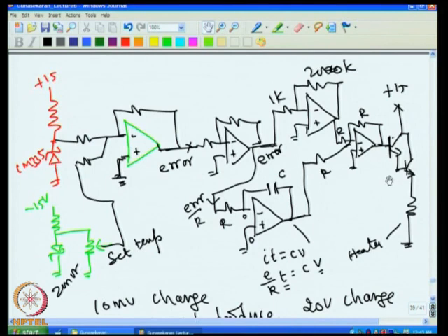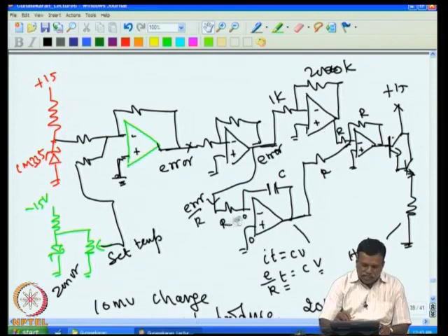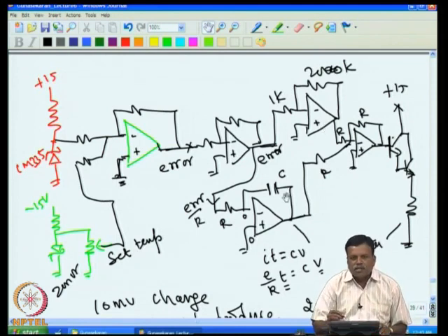That means I had to put RC equivalent to the system time constant. In this case it is supposed to be 100 seconds. For the 100 seconds, we also had to consider the same type of scaling that we had used in the case of temperature. So one can set this R and C after scaling, then only it will work.